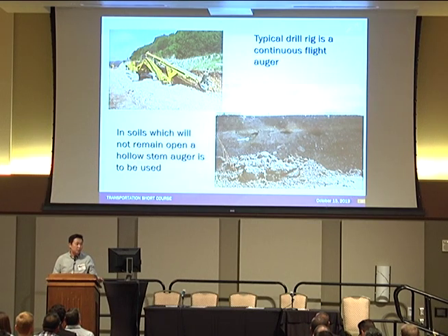Okay, the typical drill rig for a soil nail retaining wall uses a continuous flight auger. Some soil conditions require special tools, such as water-bearing sand and gravel conditions.